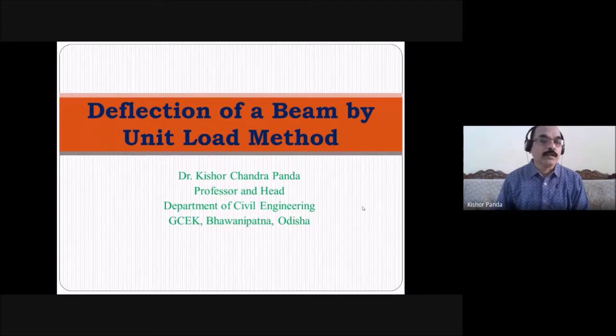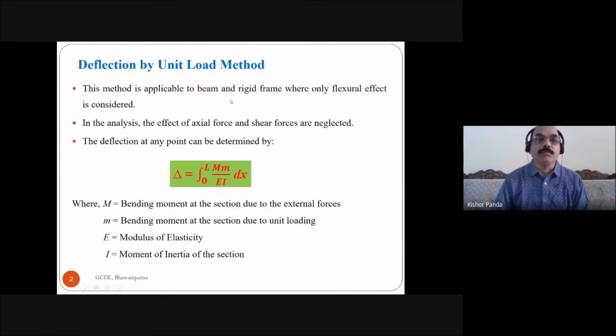Today I am going to present how to determine the deflection of a beam using the unit load method. In this method, you have to apply a unit load at a point where the deflection is required. This method is applicable to beams and rigid frames where only the flexural effect is considered. In the analysis, the effect of axial force and shear forces are neglected. And you can find out the deflection at any point using this relation.